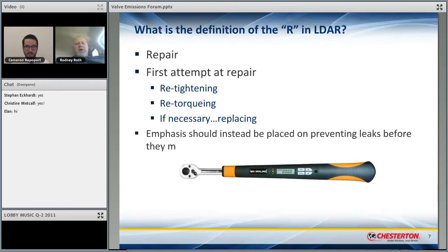So, starting with Camden earlier before we started, the next step, in all of the consent decrees, if they cannot manage the leak by retightening, they do what is called an extraordinary repair. And in our world, it's really not extraordinary. It's called a drill and tap. It's where they use a leak sealing company that actually drills in and taps and places an external fitting on, and then pumps in a pumpable packing to re-energize the stuffing box and hopefully control the leak.